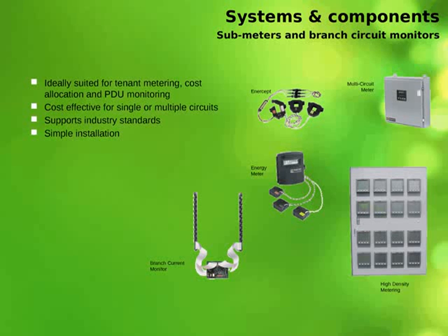These more than likely are the meter types that are going to come with very simple installations, where you either have the meter designed as a clamp-on CT that monitors the actual load or equipment, as well as something such as a high-density meter pack that allows you to monitor multiple circuits in a highly populated electrical distribution network, such as a high-rise building with multiple tenants, etc. Next slide, please.